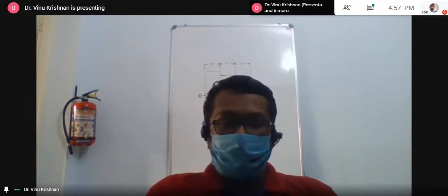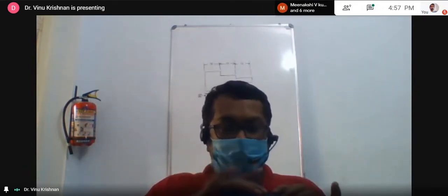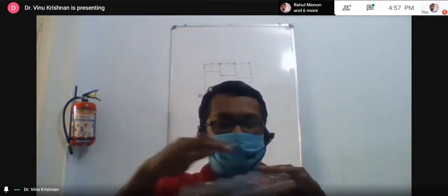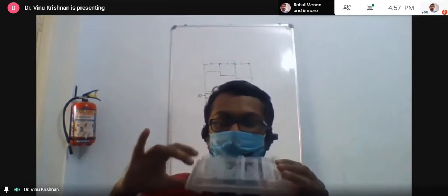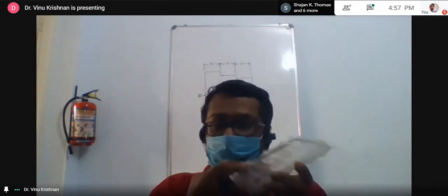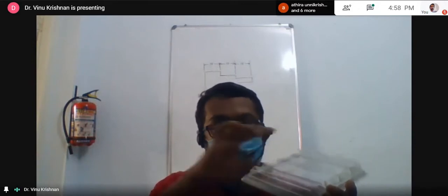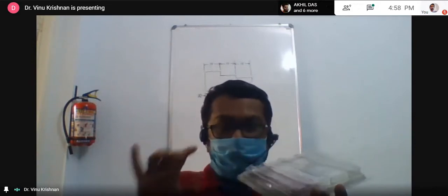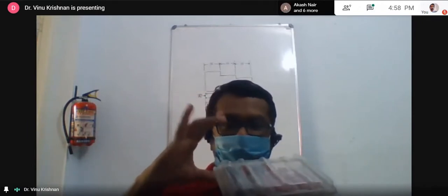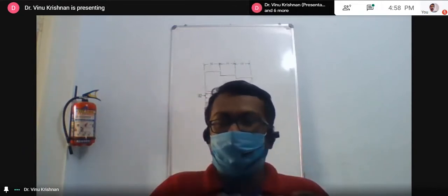Then what is profile? Profile means shape. So how this shape is, whether it is flat or something like this, you need to control the entire thing. You don't need to control each and every one, right? So you use profile. What you do is define a nominal shape, and the profile can vary from a higher limit to a lower limit, or maximum material to minimum material condition. That's how the profile is called out.